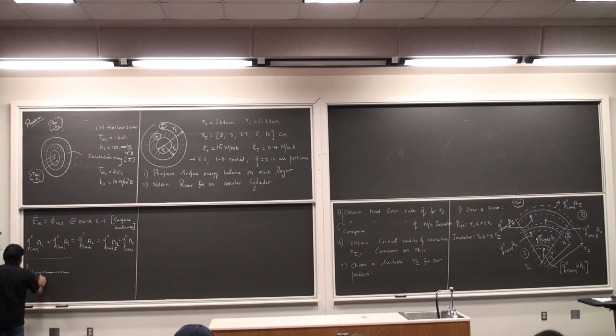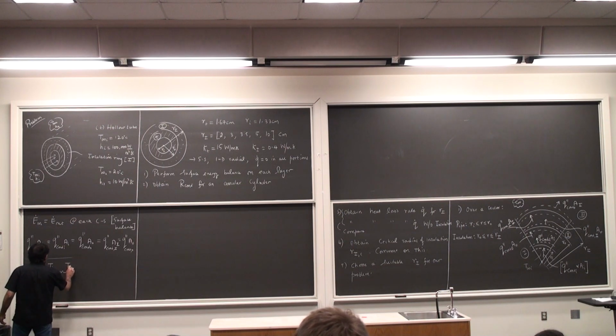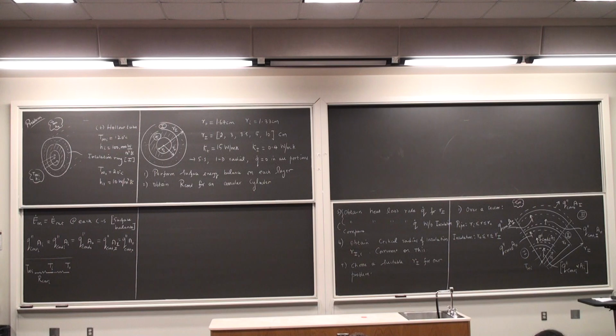So this is R convection I. I'm going to call the temperature at the inner ring T_i. Then as I have heat transfer going from T_i to T naught, which is the temperature at the outer ring of the pipe, I'm going to have a conductive resistance, which we have to find out, or conduction through the material whose thermal conductivity is given to us as k_T.